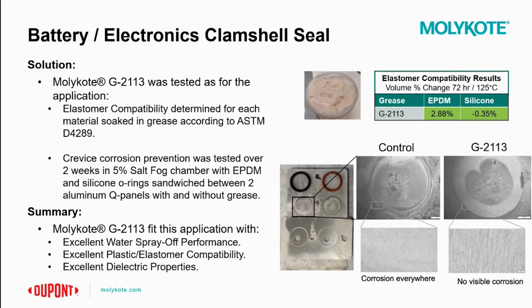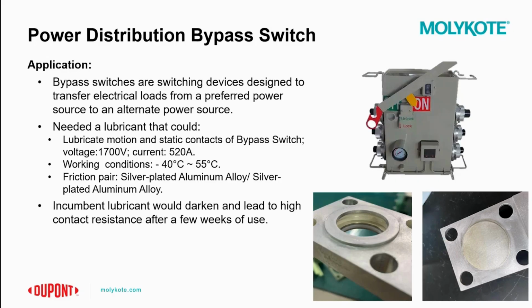With these two tests, it was found that MOLYKOTE G2113 was the best candidate for this application. It displayed great compatibility with both EPDM and the silicone elastomers, while also providing excellent protection from crevice corrosion and resisting water spray off to ensure it stays adhered to the application. For our last case study, we take a look at power distribution.